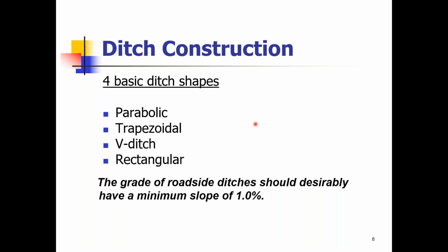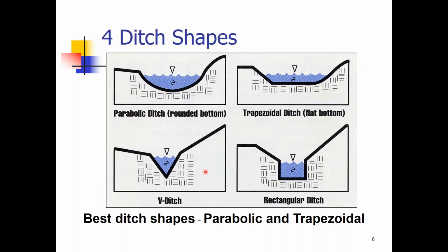What we do not want to have happen is have ditches so deep that vehicles cannot have an opportunity to get themselves back onto the roadway should they run off the road in some form or fashion. If there's an immediate drop right there into a ditch, then that motor vehicle has no opportunity to make that correction. And we'll look at that here in a little bit.